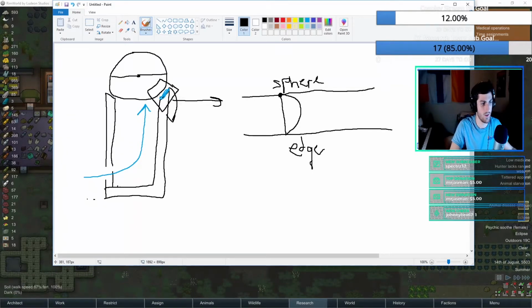So it turns out that because of the lubrication, the force that this fluid can exert on this ball is actually extremely efficient and high enough that you only need about 8 psi gauge. So the pump needs to be 8 psi. So you only needed 8 psi to support 29 tons, which is crazy. For reference, atmospheric pressure is 14.7 psi.